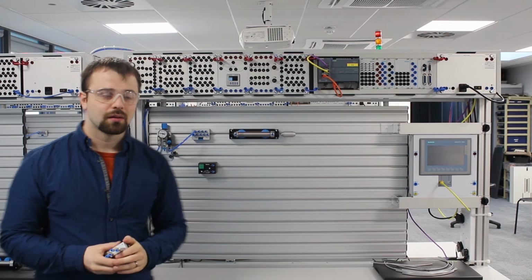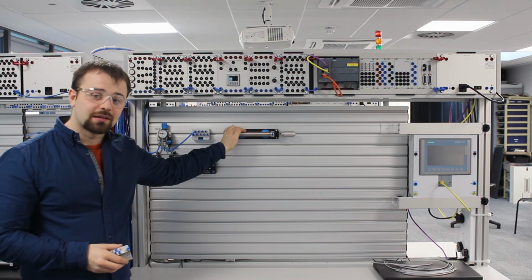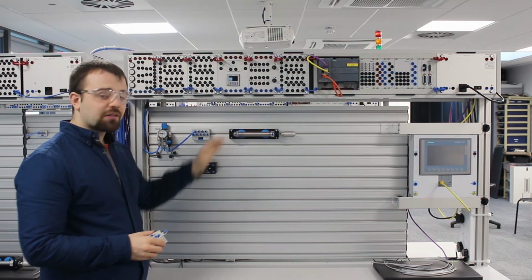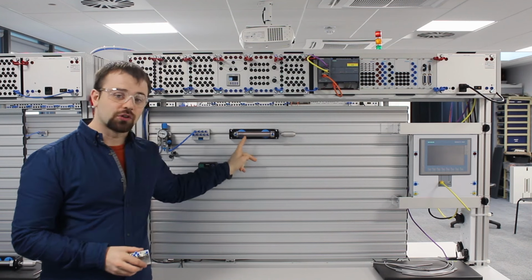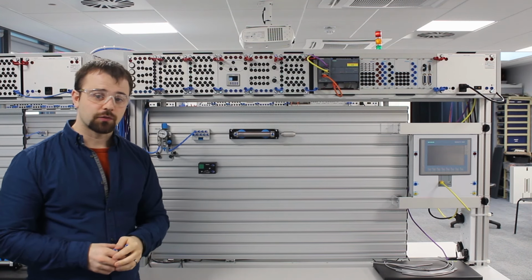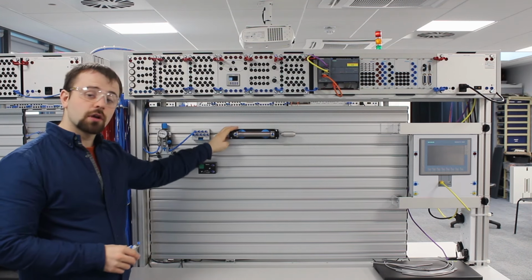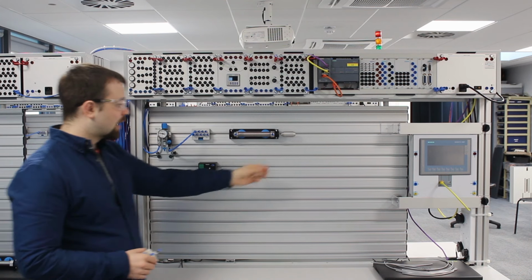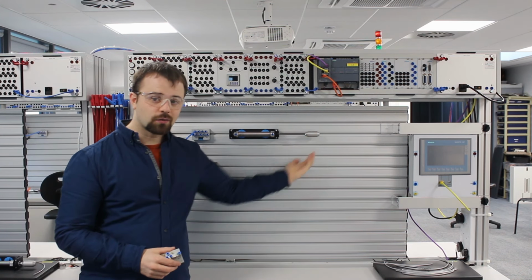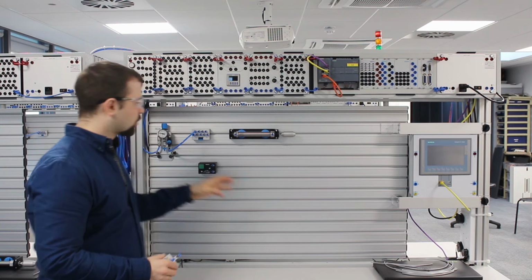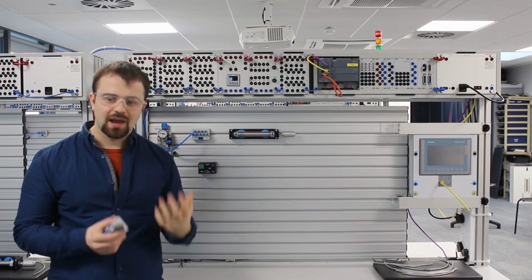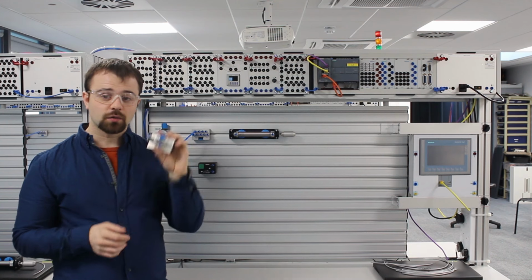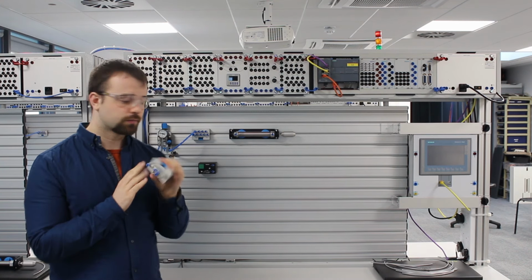Okay, so here we are. I've put our double-acting cylinder up on the board. As you can see, this one actually has 2 ports on it, unlike the single-acting cylinder we had before. You'll also notice there is no spring inside this cylinder. If I move it forward, it stays out until I push it back. So it's not going to go anywhere without us telling it explicitly where to go. So that's why we're going to be using this directional control valve.